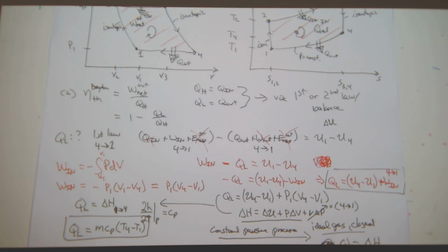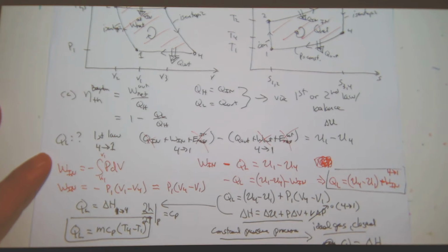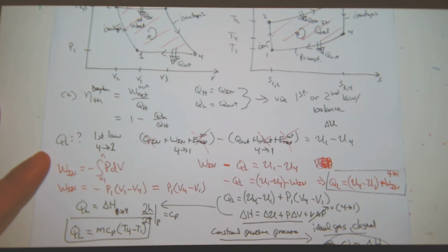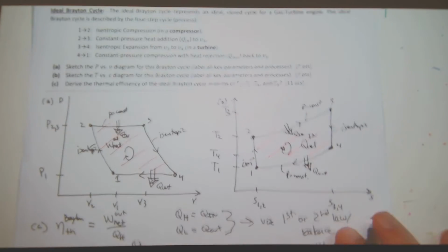Because I know in the diesel cycle, we had a constant pressure process at the top. Yeah, with constant pressure, but that was QH, not QL. Yep. So given that I already did this twice, so I have this QH, right? I need to know QH is what, and that's from 2 to 3, as shown here.